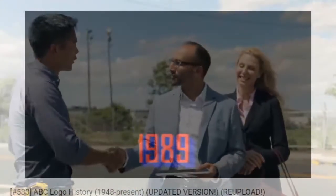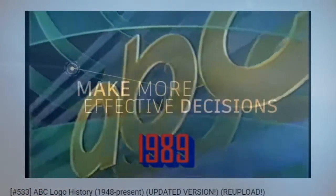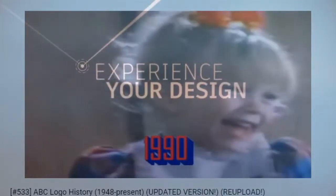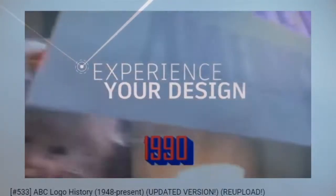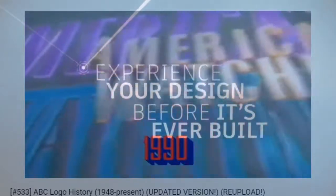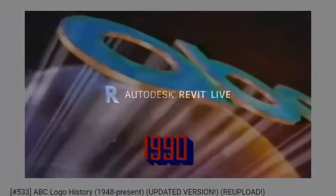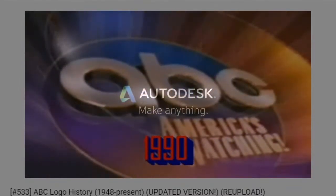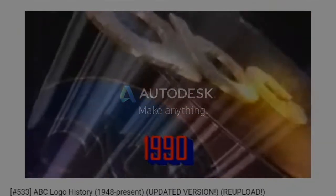Completed application of carpet tile material to a split face of a floor. Click the Done button in the material browser to exit the paint command. And we've done that already. There it is applied. You can see it now. Rendered, you can see it a little better, to a certain extent. All right, so that's a pretty brief explanation of the split face.